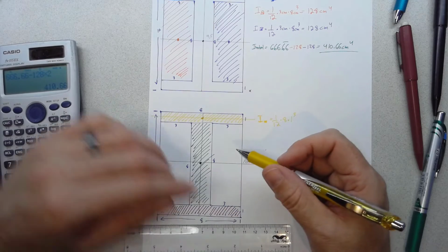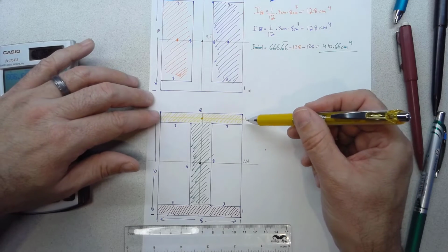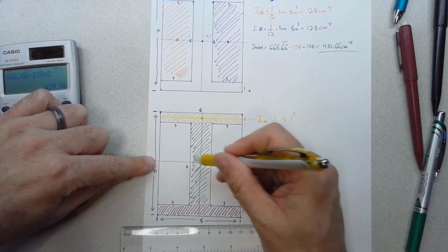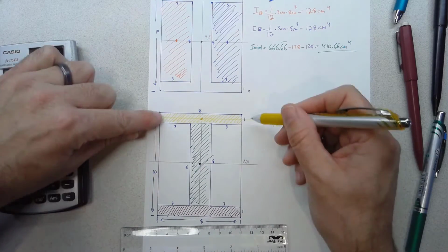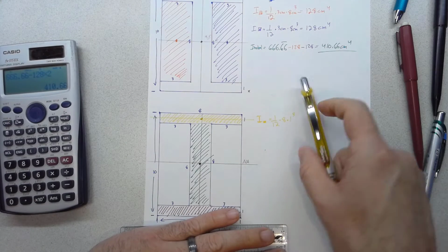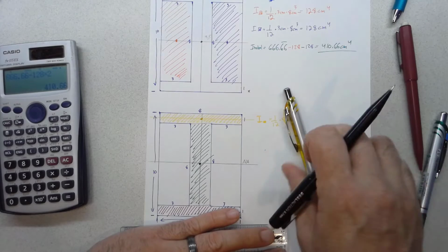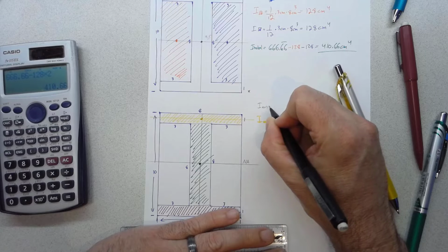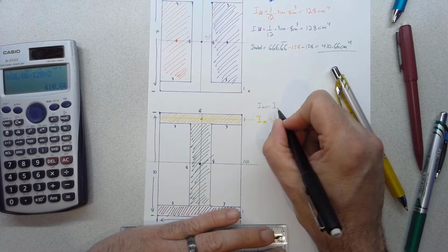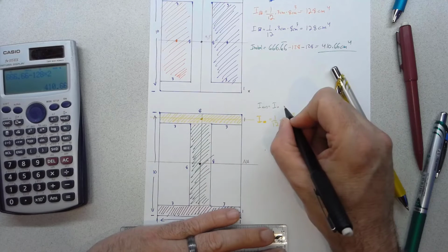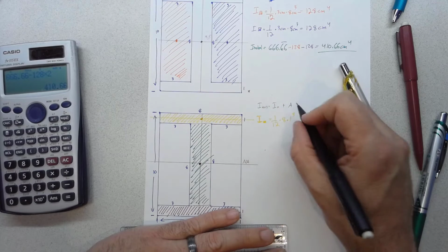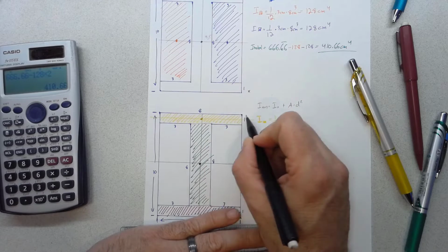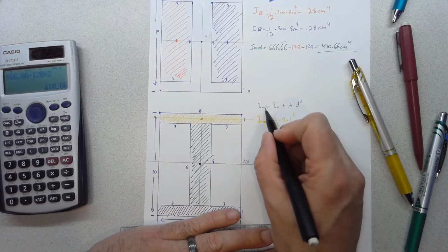So now I do need to use the parallel axis theorem, because I want to know what contribution this 1/12 times 8 times 1 cubed has about this axis, an axis parallel to its own centroidal axis, but some distance away. So remember the terms for the parallel axis theorem. Let me write that right up above it. I about some axis is equal to the component I about its own neutral axis plus the area that we're working with times the distance squared. And the distance is the distance from the centroid of the area that we're looking at to the axis that I care about, to this axis.